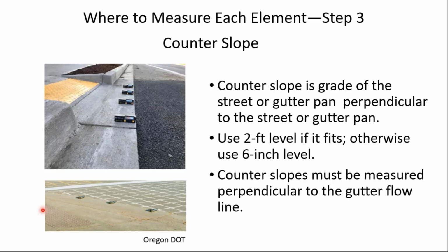Let me see. From Jared, what's the current guidance on diagonal versus straight intersection ramps? Are straight-oriented ramps preferred, or is it expected that PROWAG will require them where possible in a future update? Well, what's required are the types of ramps I've talked about here. The single diagonal ramps are not permitted in PROWAG, and so we shouldn't be building any new single diagonal ramps. They may be acceptable in alterations if it's technically infeasible to use one of the other 3 types of sidewalk to street transitions.